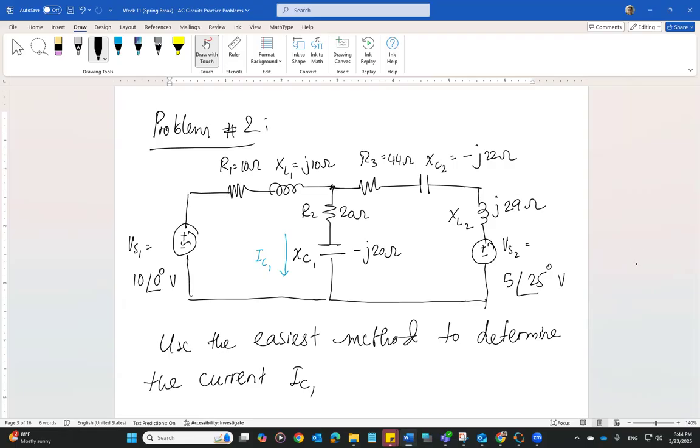So what we're going to do is, again, analyze the circuit, a very simple circuit. You have two sources given, and when two sources are given in sinusoidal form in a steady state sinusoidal circuit, we assume both sources have the same frequency. If they do not have the same frequency, then the frequency must be given for each source, and then your reactance value is going to be different for each source, because reactance depends on the frequency of the source. And in that case, reactance values will not be given to you.